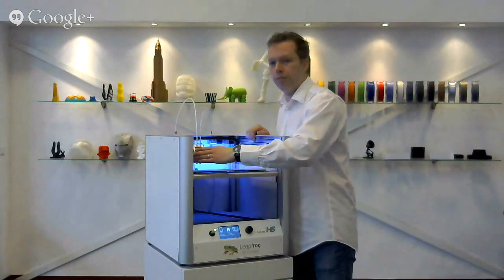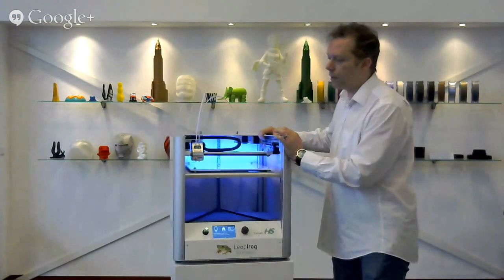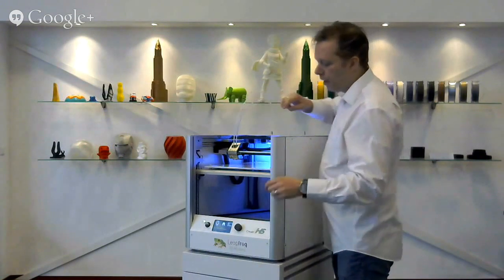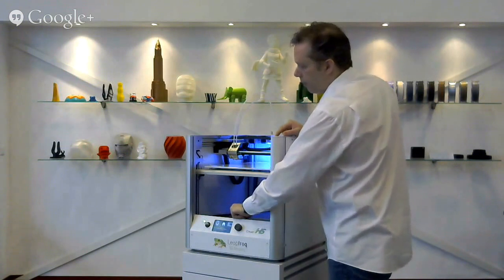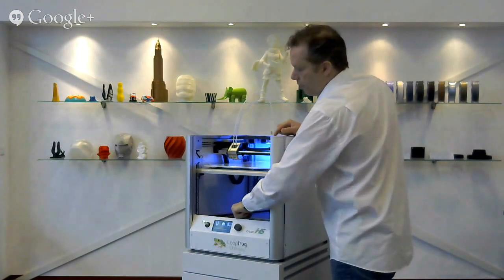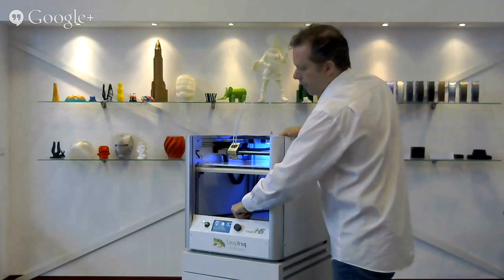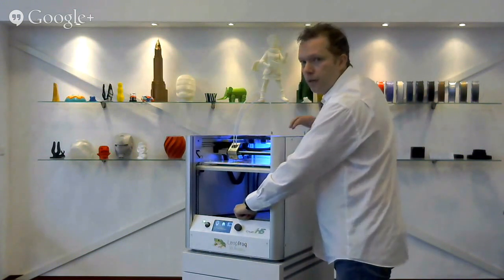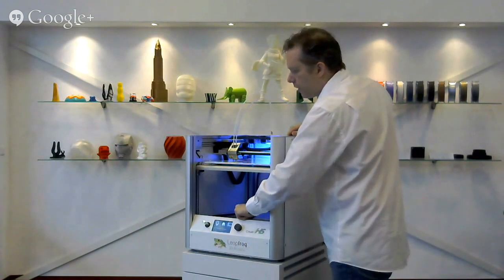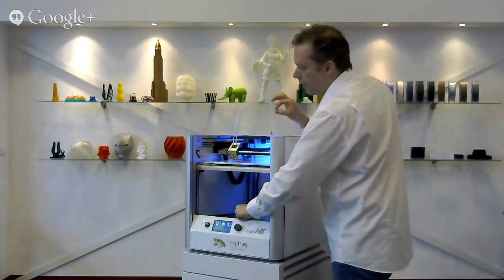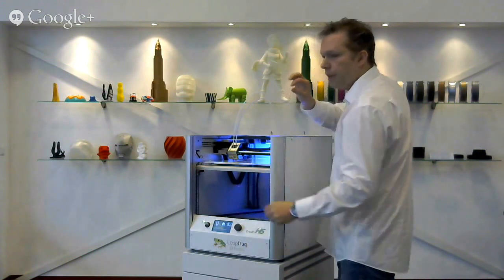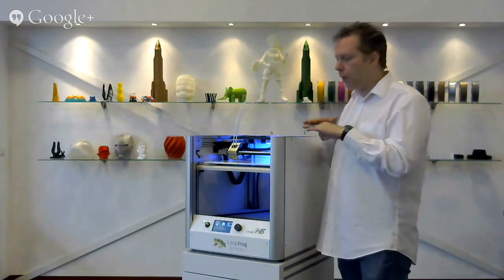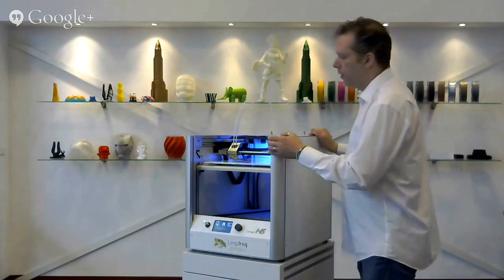First, you move your head backwards, and you can see inside the printer there's a small Z sensor. If you move your timing belt on the bottom gently, you can move the bed up. And if you move the bed up until the sensor light, there's a small LED on the sensor, goes on, find the exact switching point where the sensor goes on and off. And then you found the exact point where the printer will stop.